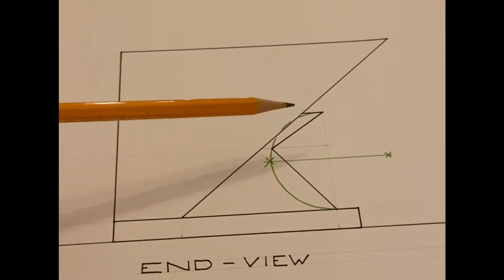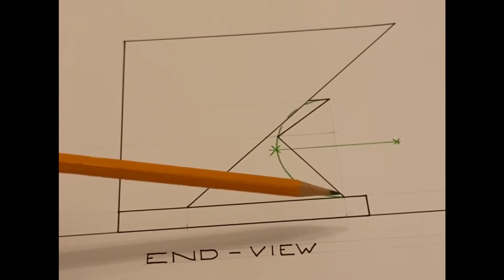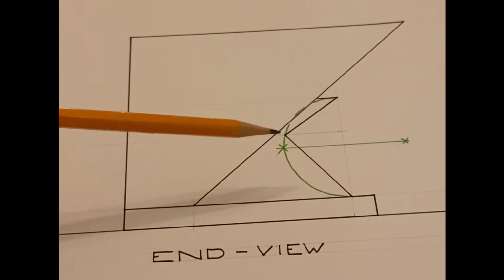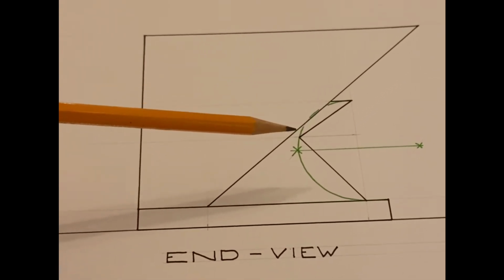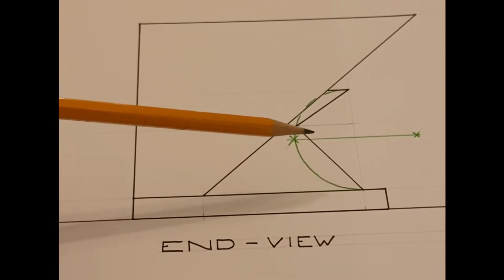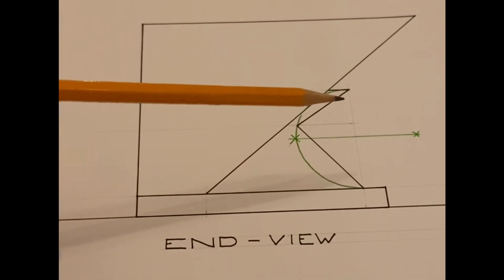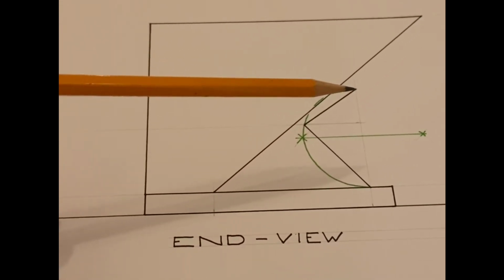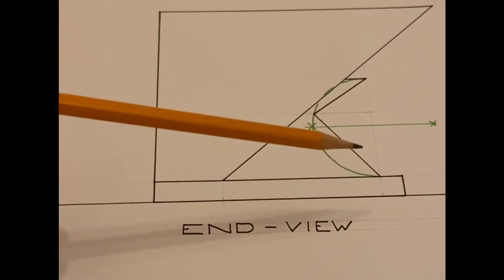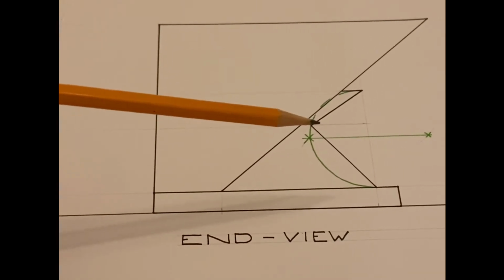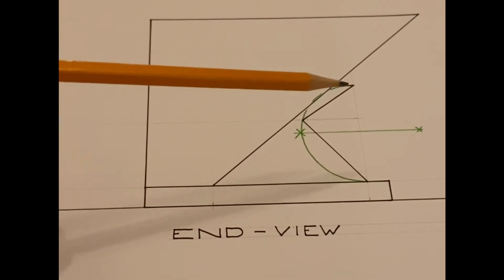Okay, so the distance from here to here is 55 millimeters, and we know that this point is up 35 millimeters and that this angle here is a 90-degree angle. Any time you see any mention of a 90-degree angle, you should instantly think of a semicircle, because if you join from the end of the diameter up to the circumference and back down to the same diameter, this angle at the circle is always a 90-degree angle. So in order to solve this, we have to draw a semicircle.